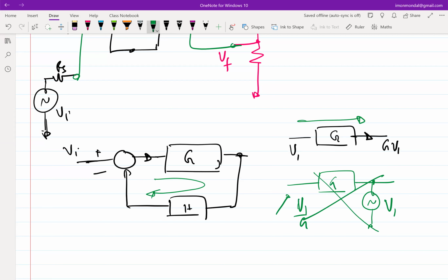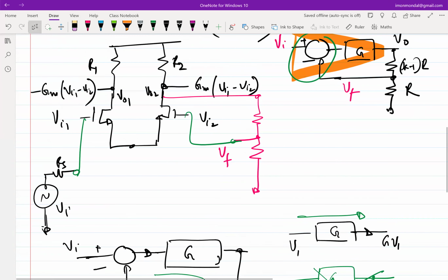In a block diagram, it is easy to make, but in reality, none of the elements that you know are unidirectional. For example, for a resistance, a signal can flow in either direction, right? For the capacitance, signals can flow in either direction. But fortunately, in a transistor, if I assume one of the terminals to be the gate, the signal flows only from the gate. I mean, it is sensed at the gate and then something happens at the drain and source, not the other way around. So to some extent, I can say that a transistor is also a unidirectional device.